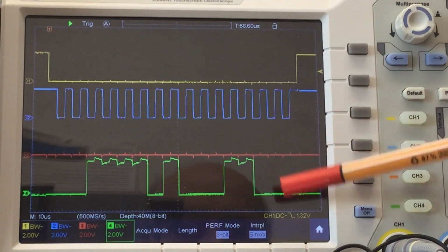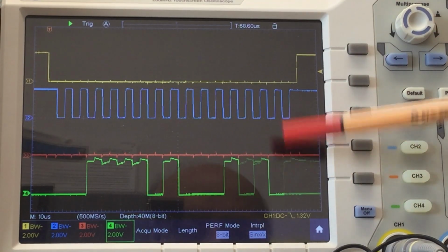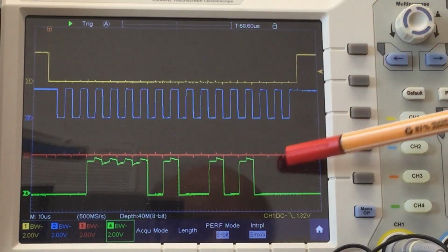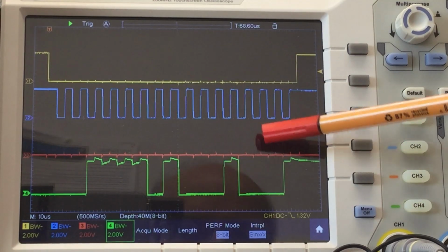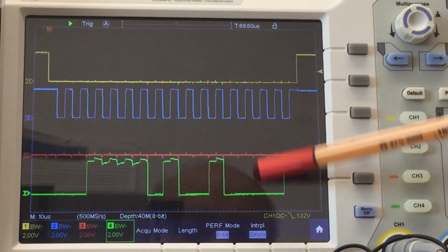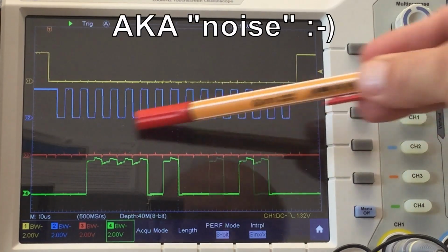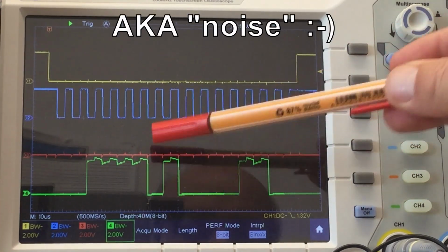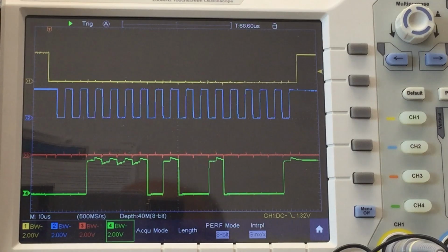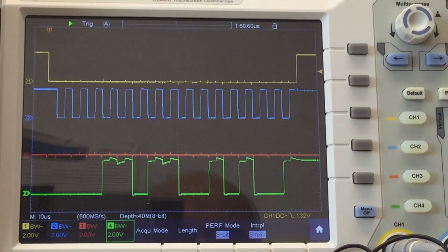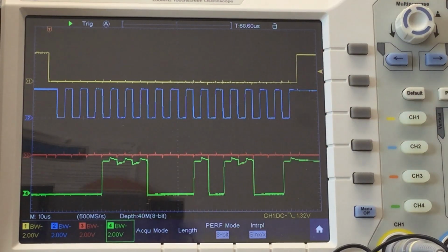Note that the last bit changing here is just our parity bit, and then this is a 12-bit value in total, as we have seen in the code too. Only the last few bits are changing, the least significant bits. The most significant bits stay stable unless I turn the wheel, and then we get, of course, another value here, turning it again, and so on.